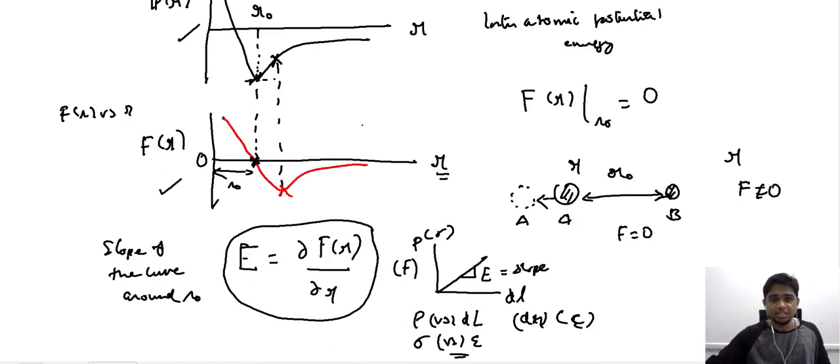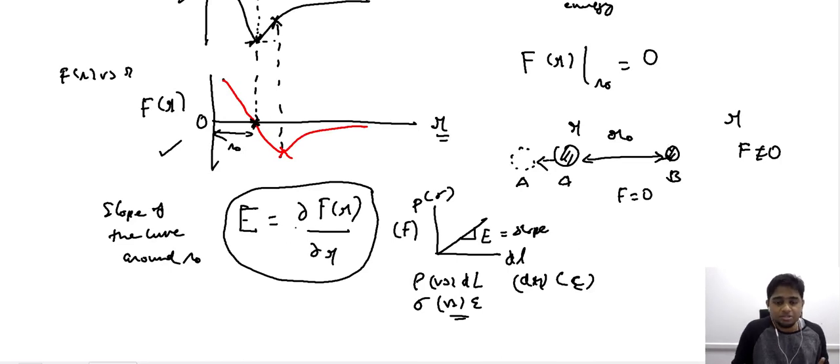Besides all this, this expression here helps us to quantify the Young's modulus, one characteristic property of a material during the elastic deformation, in the elastic regime of the mechanical behavior. The characteristic property of the material is Young's modulus. This Young's modulus can be calculated from the atomistic perspective. So the atomistic perspective gives us an explanation of the elastic behavior, why a metal should go back to its original state when it is deformed.